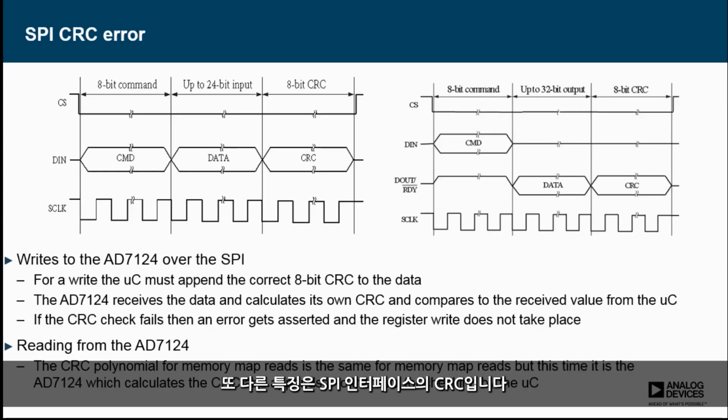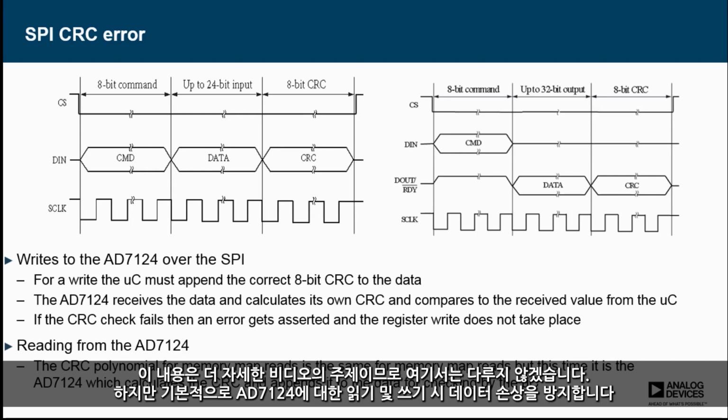Another feature that I want to bring to your attention is the CRC on the SPI interface. This will be the subject of a more detailed video, so I won't go into it here, but basically it protects you against data corruption on both reads and writes to the AD7124.